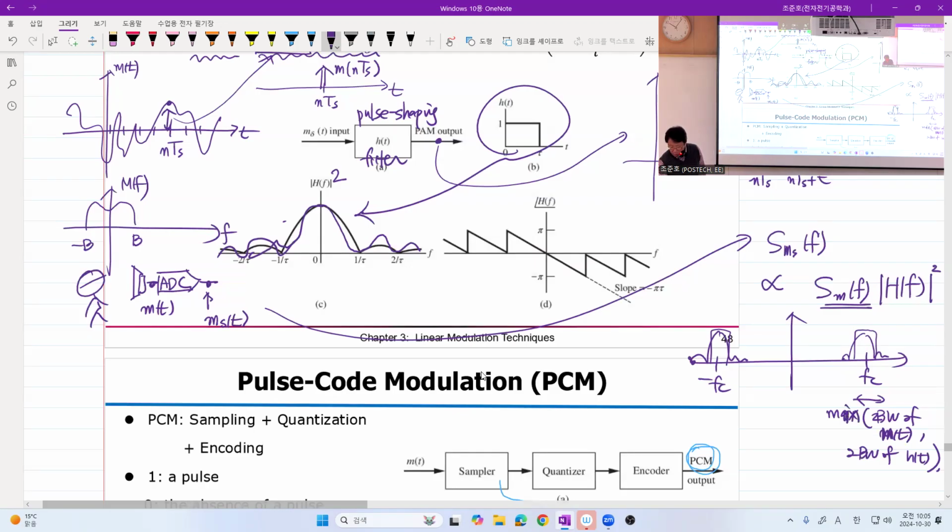If we assume the speech signal is band limited, then after some frequency offset, the energy spectrum of the voice signal is 0, then 0 times some ripple of this sinc square is almost 0. So we are not occupying infinite bandwidth. However, we occupy a significant part of the bandwidth.